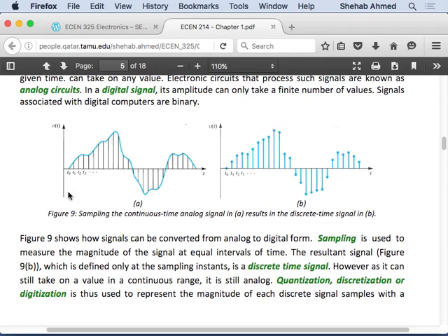Okay, so this is, again, my original analog signal. And these are the time steps at which my computer operates, my digital signal operates, right? At every time step, I'm going to sample the signal using what is called an analog to digital converter. This analog to digital converter will quantize my signal. So between this point and this point, I only have in memory this last value that I have here, right?